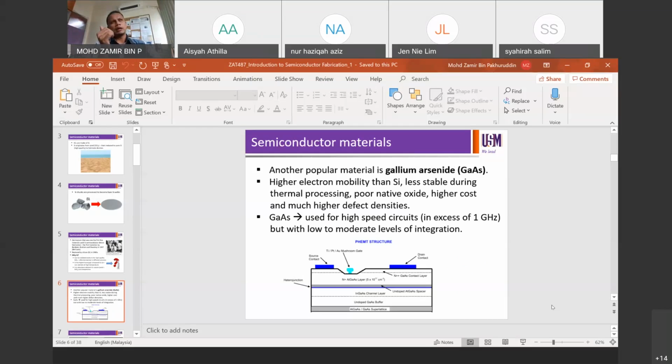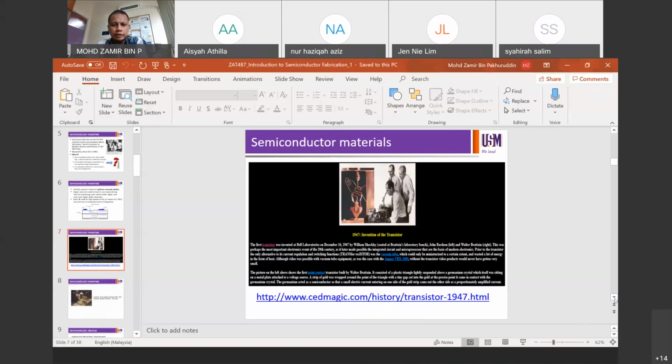we can see that the average electron mobility for gallium arsenide, for example if you choose 1e18 per centimeter cube, the electron mobility will be higher for gallium arsenide in comparison to silicon. So that's why we use gallium arsenide for a higher electron mobility transistor, or faster switching device. Okay, so it's usually more favorable than silicon.